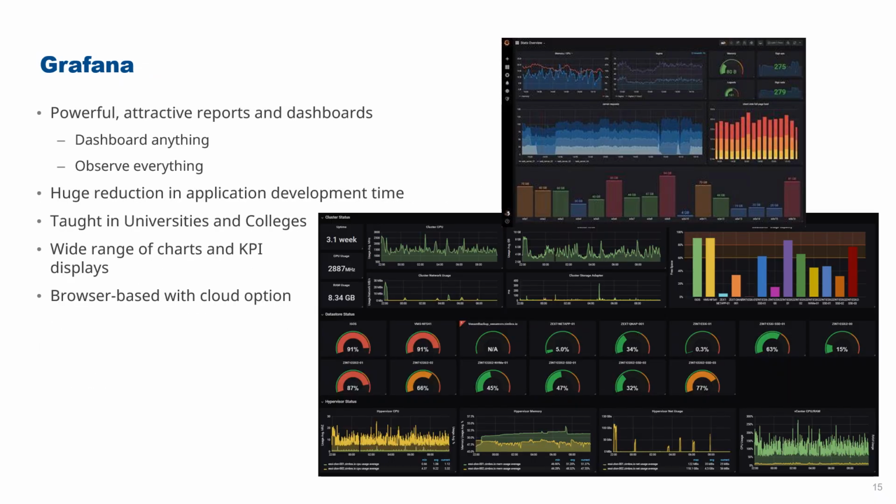The other area where people might be doing a lot of work is in the dashboards and reports. So this is why we've included Grafana. I mean, you could use Node-RED. Node-RED does have a dashboard capability, and for simple applications you might stick to using Node-RED. But Grafana has the option for more powerful, attractive reports and dashboards, and it gives you the ability to get any data, locally or remote, SQL, OPCUA and other forms, and you can dashboard